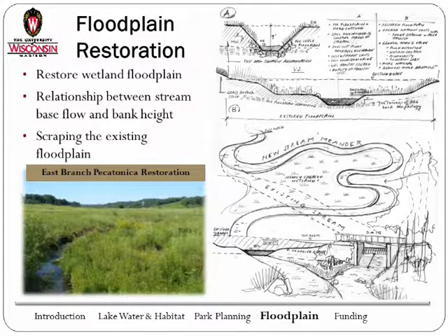And then to step back just a second again, this issue of restoring a floodplain. How do we do this? And so, as Sam was mentioning, we have this wedge effect of sediments that have built up behind the dam. If we divert around the dam, we've got to reconnect those 2 streams. And there's about a 7.5-foot difference, that vertical difference. So that would mean that we'd have to cut through this wedge of sediments, which would look something like this if we didn't remove the soil. This wouldn't be a very well connected relationship between the stream and the floodplain.